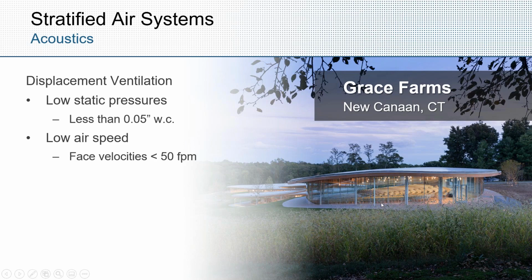For very wide spaces, more than 60 feet is the typical rule that we like to follow, you want to get the air to the middle of the space, and oftentimes you'll see round floor diffusers placed underneath every other seat. That is enough air in most cases to supply and condition that entire room, so that solves a lot of design challenges.